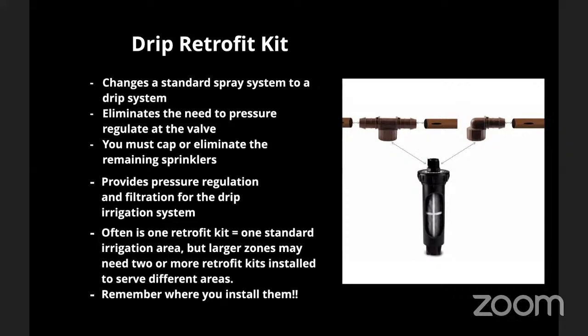So you refer back to the slides. Remember, I provided how many linear feet you can do off of a single 1/2-inch connection. If that linear feet or that square footage is smaller than the area you're irrigating, you can just connect from one area of your irrigation system and cap off the rest of the sprinklers to this.